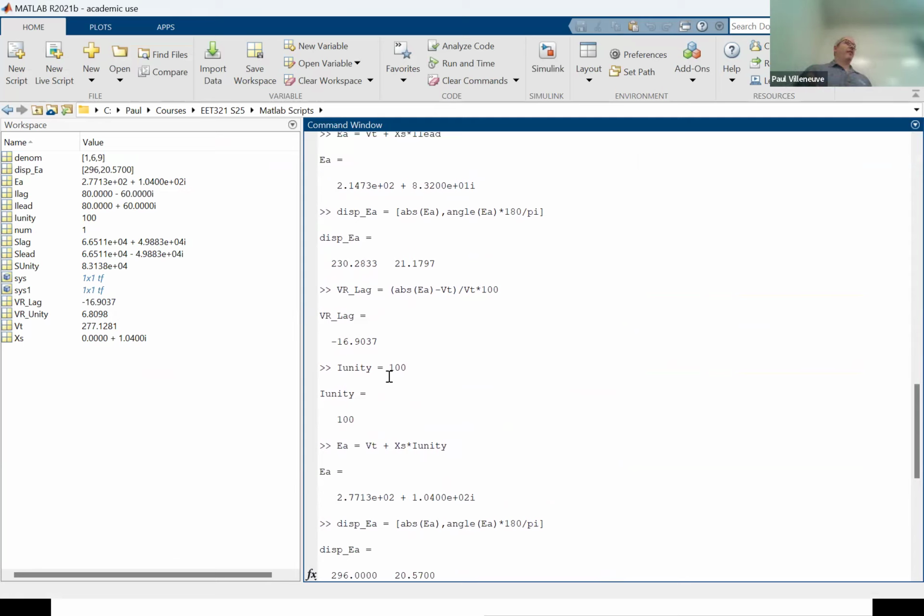And that is one of the things that sometimes power systems are limited by, which are not necessarily the technical things, like I'm going to burn the conductor up. It could be that I'm worried about too much of a voltage drop. If the system goes down, then that voltage flows on the system so high that I can cause fires in people's homes. So they can limit it. A lot of the grid is actually limited not by the power ratings of the equipment, but by more administrative things, if you will.